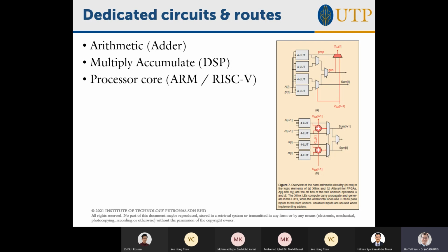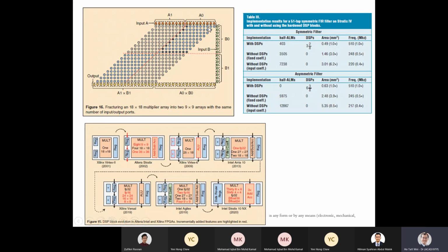Okay, so multipliers are actually implemented with dedicated circuits in the FPGA. This is just showing you an example: I have one digital number A and another digital number B, and I'm trying to multiply A and B. The way I perform digital multiplication is I take all of A. If the first bit of B is 1, I set this all 1. If the first bit of B is 0, all of this becomes 0, right? Then I use the second bit and shift it, and do all of this, shift. Then I'm doing addition this way, right? This is how multiplication is implemented digitally.